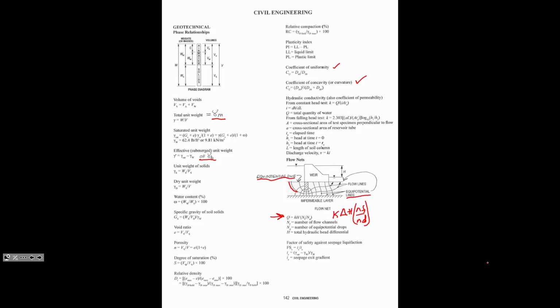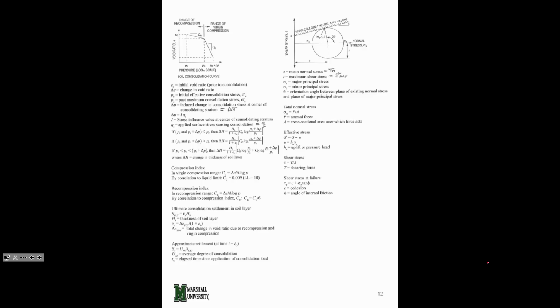I've never seen a seepage liquefaction question on any practice stuff, although it could be there. At the top here, we've got a compression curve like I had on my other sheet, showing where C sub C and C sub R are. C sub R, yeah, that sounded really good, didn't it? And we've got our different equations depending on where we start loading and where we end our loading. So you just have to follow the if, and that tells you which equation to use.